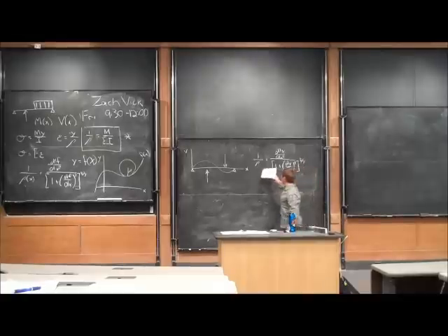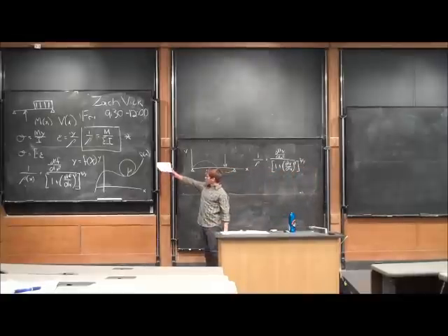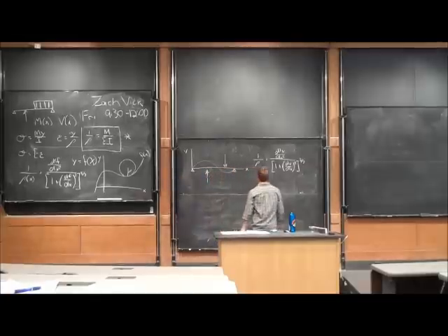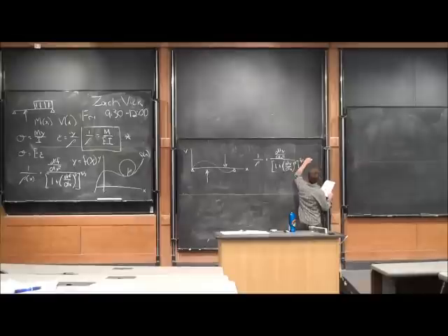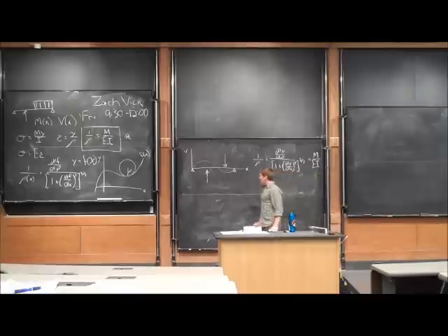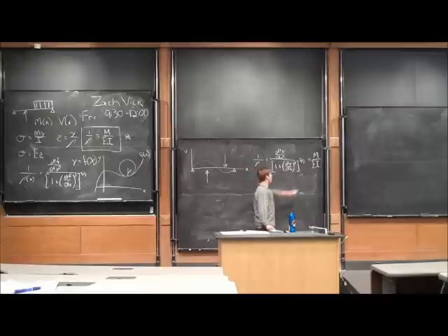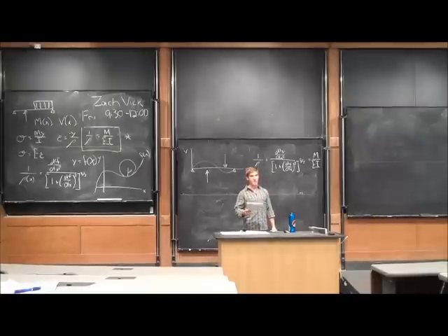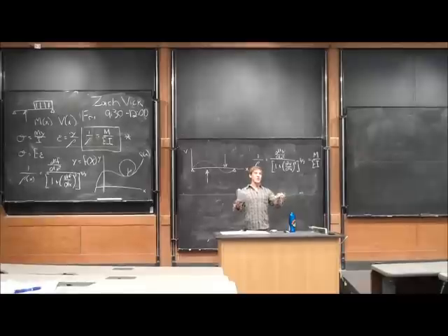Now, if we equate 1 over the radius of curvature to what we used to prove bending stress last week, we also see that that's all equal to M over EI. So now we can predict what the deflection of the beam will be at any x location due to the moments that we can find at that location in x. So depending on what that moment is, it'll give you a greater radius of curvature and a greater deflection for a larger moment.